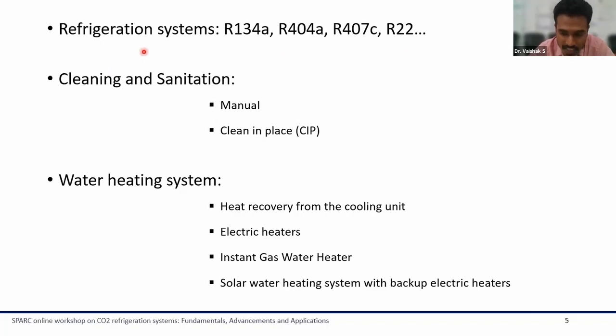So once this milk is pumped to the transporting trucks, all the components in the collection center have to be cleaned, and this is a very important process in this supply chain, because the next batch when we are loading should not get spoiled with the bacteria or the remainings of the previous batch. This cleaning can take place through a manual process or through a clean in place process. In the coming slide, we will be looking in detail at what this clean in place process is and what the temperatures involved in this process are.